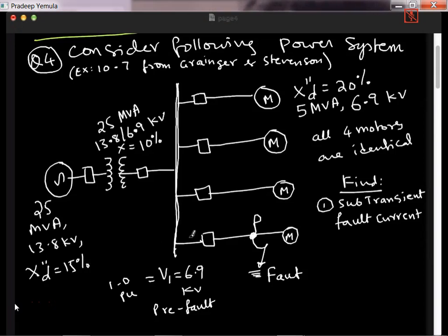All right. So this one, these are all circuit breakers. So this circuit breaker is called circuit breaker number A, because that's required for the next question. Subtransient current in breaker A. Now the fault current I have to calculate, that is I fault, whereas the current in the breaker, let's call it I capital A, breaker A current. Now you can ask, how come they are different? Fault current and breaker current should be the same, but in this case they are different.